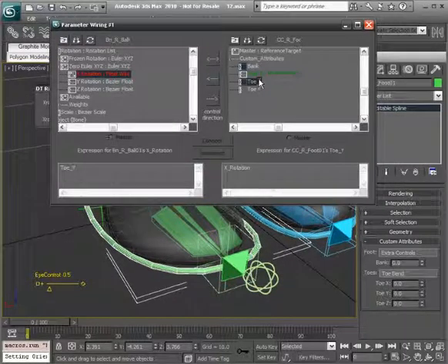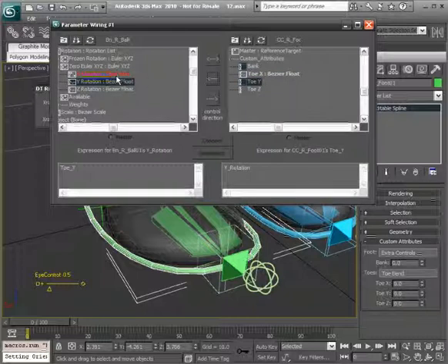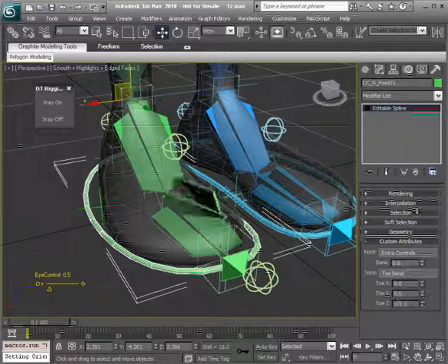Okay, so let's go ahead and finish up here. Again, we use that middle arrow connecting to not our X, but this time to our Y, Y to Y. And be very careful of that. Okay, so again, use the arrow, connect to the Y, degree to radians, and then choose connect. If you wanted to, you could always copy this, connect, go to the Z, do the connection there, paste, and just simply change this Y to a Z and update. And there we have it.